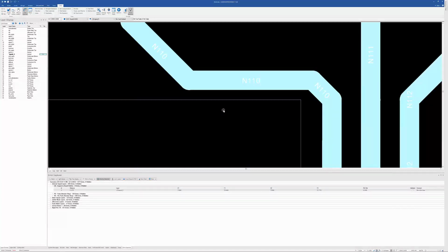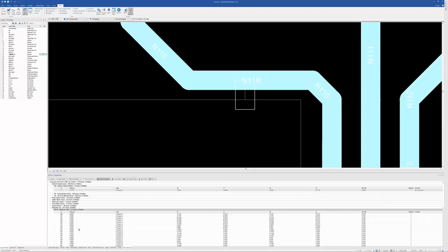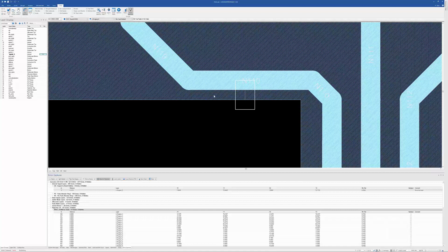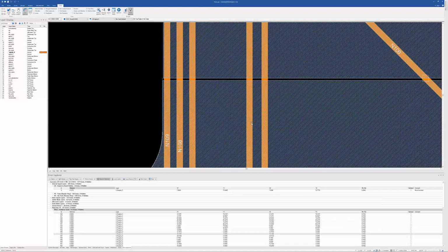All right. Again, going through these checks, let's take a look at the rigid flex checks here. Profile to track: these are those layer profiles. This is one, and this is another, and I got a trace going through both of them. Well, that doesn't work. Okay, so that's why that's called out as an error.